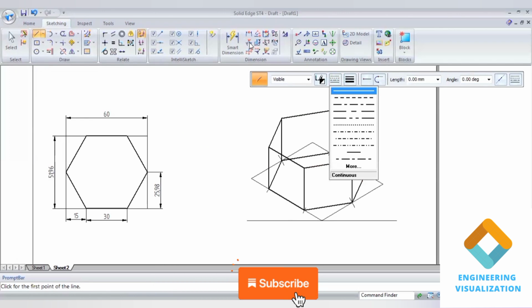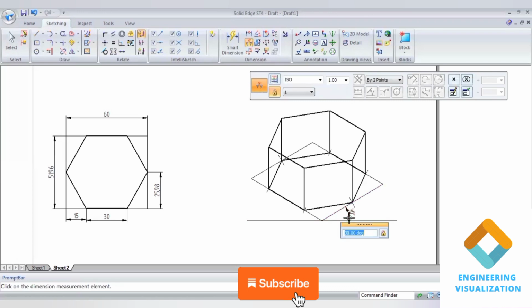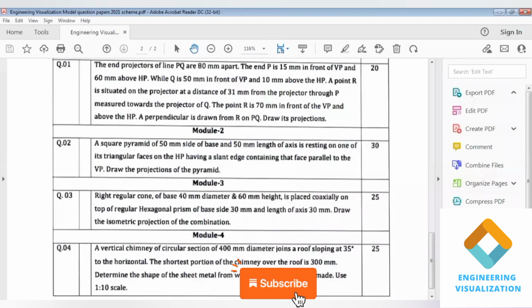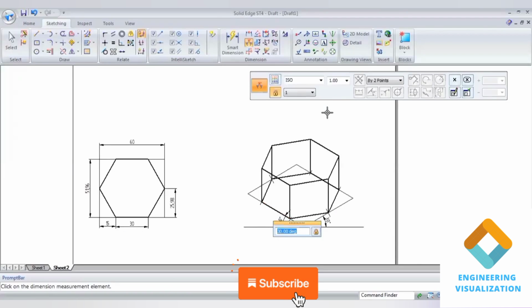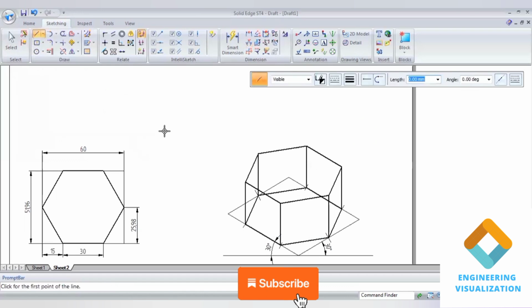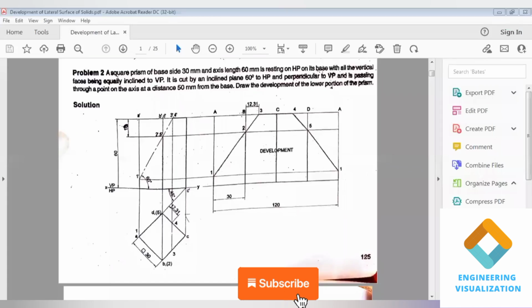Okay, so to place the cone here separately, what I'll do, I'll be constructing the hemisphere, that is, the ellipse of dimension 40 separately. You can see a right regular cone of base side 40 mm. Okay, on one side I'll be constructing by taking length. The length will be 40, angle is 30, and again length is 40, angle is 150, length is 40, angle is 210.